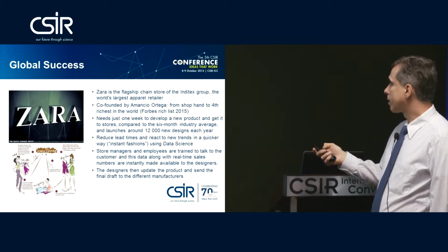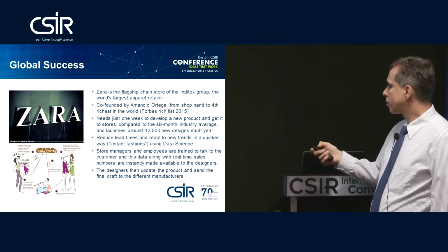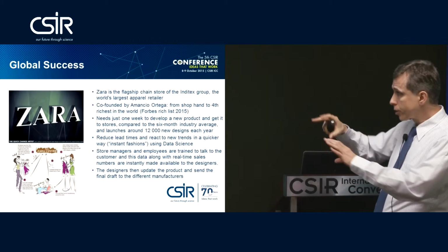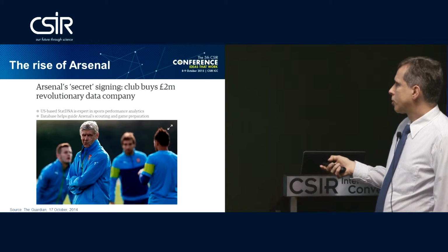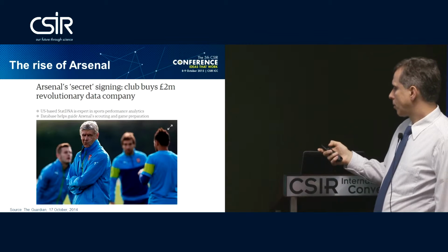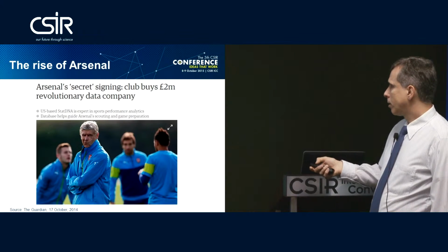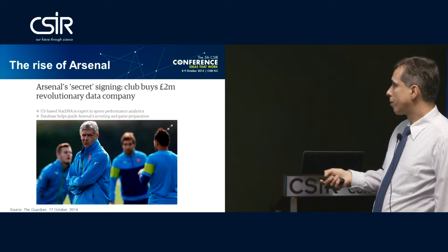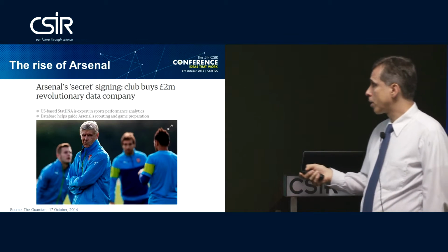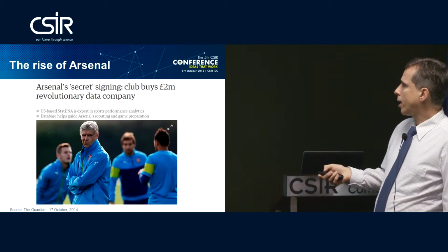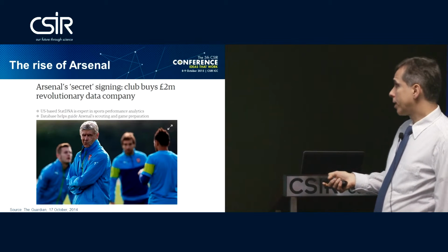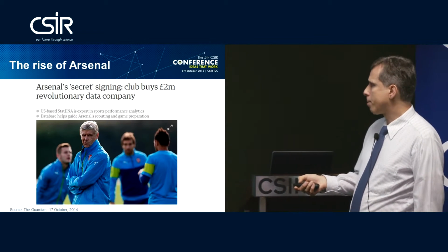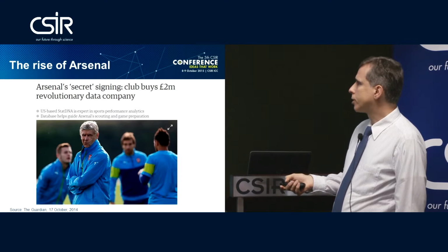get a better map from that, which we can do because, assuming we haven't moved too far, there's some overlap between these two scans. So if we can match those, we can do a couple of things here. We can first get a better map. Now we have, in this case, a full view of this environment. Our position at point A and our position at point B are now related. So the transformation that we get by this scan matching, first of all, develops the map and also gives the robot location within the map.